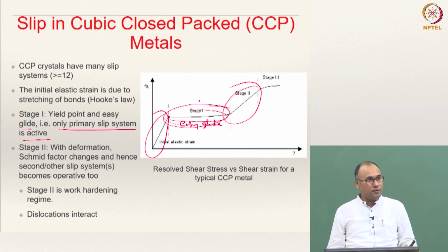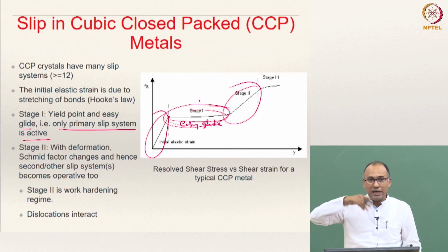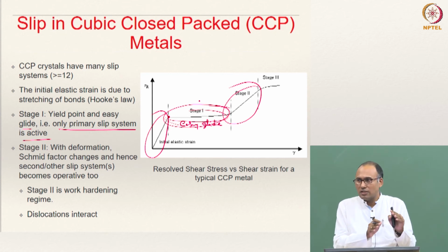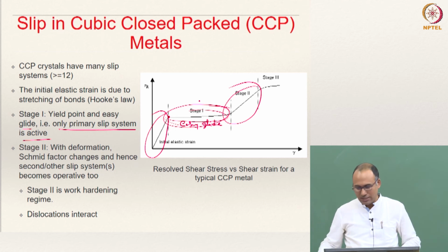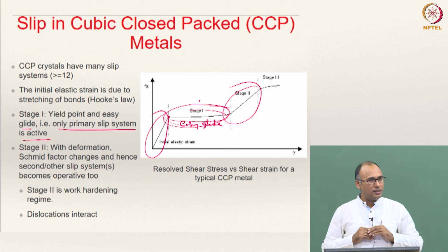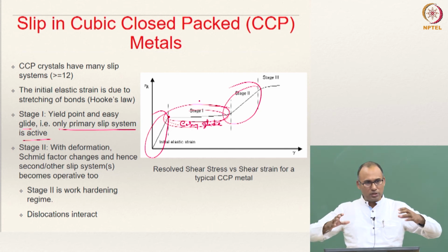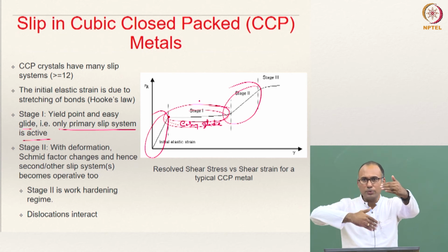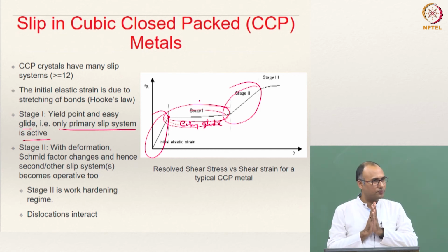Even within one plane, you may be increasing the density of the dislocations, and as a result, what happens? If you have one dislocation, this guy happily moves. So imagine this example. We have discussed the carpet example, right? When you create a hump, you can easily move the hump towards the end to cause unit slip.